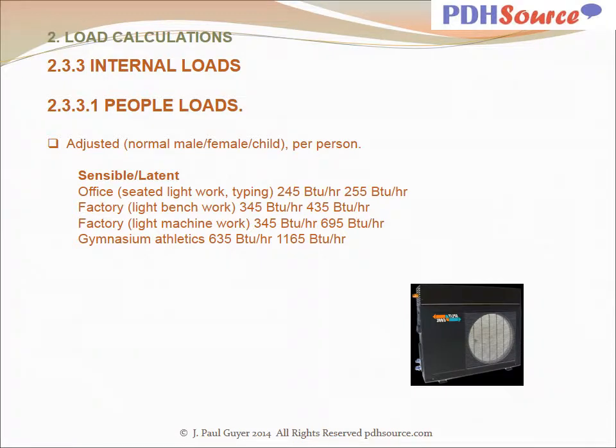In doing the calculations of the cooling load, in addition to the loads that we have already discussed, the cooling load due to transmission through the walls and the ceiling and through the glass, and the ventilation cooling load due to the outside air you intentionally bring into the building for air quality purposes, and the infiltration load, which is the air that gets into the building inadvertently.